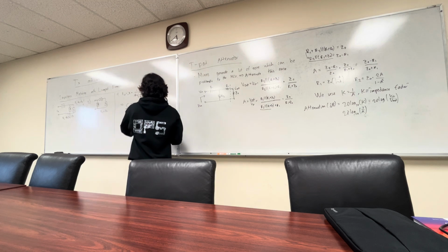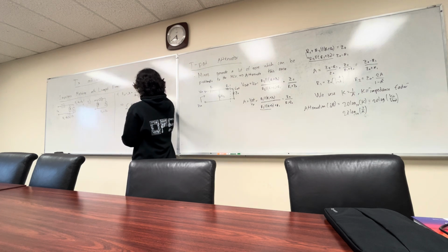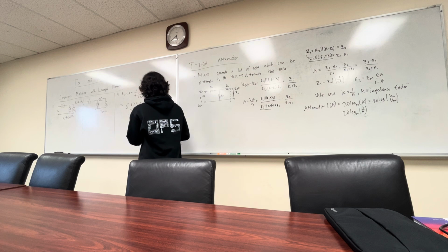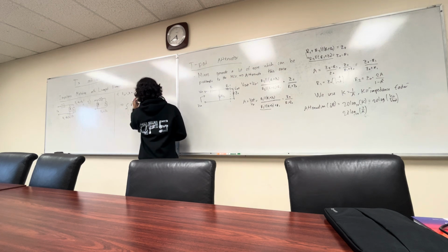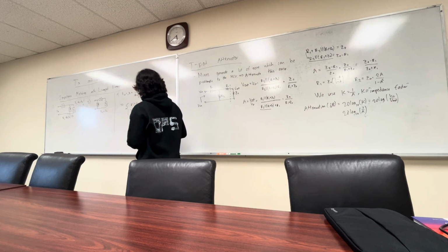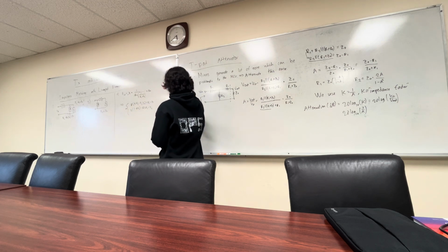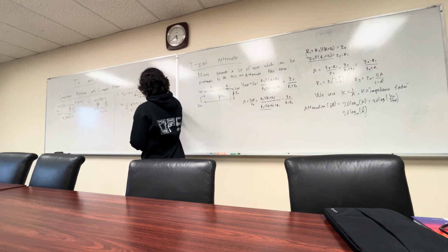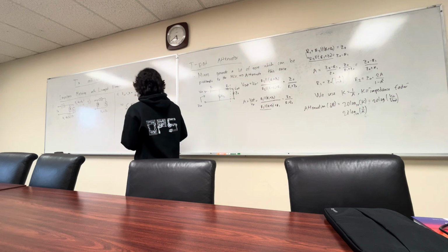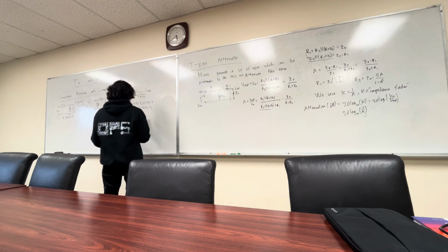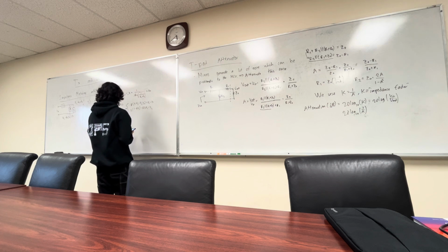And these two are effectively just matching the real and imaginary parts. When you go through this math, do it all out, and make sure imaginary is on both sides, the coefficients are the same, so you get this relationship, and then real parts get this one. So from here, now solve for B, our little susceptance.